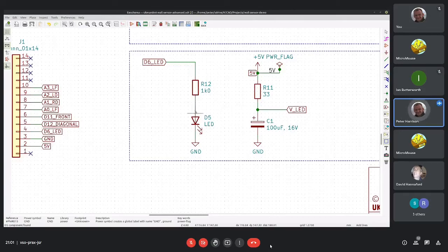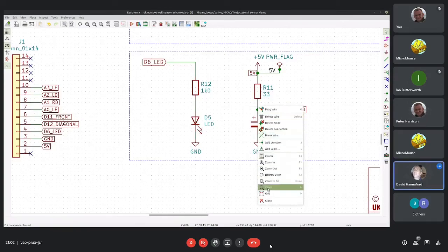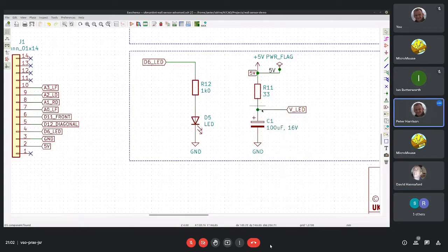So you'll see this on the circuit board in a minute. There will be a net somewhere, almost certainly, which just says that it's connecting R12 to D5, and it doesn't care what it's called. But this one, because there is a label associated with that net, will have the name on the circuit board. And I don't think it will. Well, I can't even edit it now.